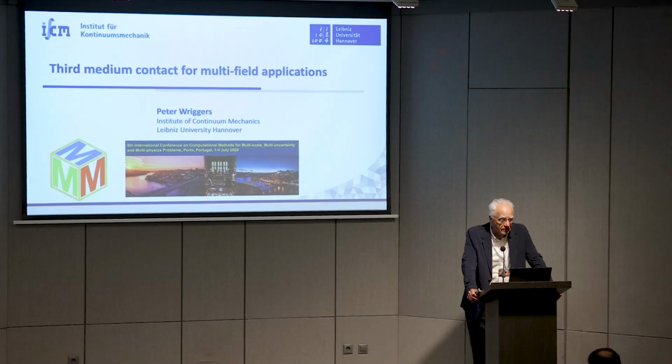And this one which I'm talking about today, the third medium contact, has some specialties, and it's actually a very simple way to enforce contact constraints by using this kind of third medium. I have extended this in this talk to multi-field applications, especially thermomechanical contact. So first I will give some ideas about the third medium contact, and then we will see how it works for the multi-field application.